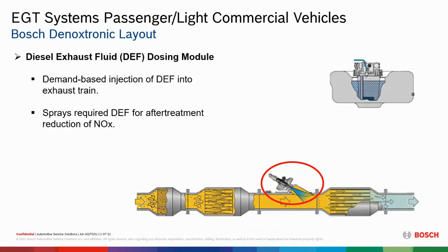And the reason I'm saying that is it's happened. These sensors may fit into another dosing unit if you take it apart. Unfortunately, some of them are very similar. They don't look any different, but the part numbers are different. So it causes performance problems, and it really drives a technician in circles, just trying to figure out what's wrong with it if it's the wrong part number, because you have to disassemble it, match the part numbers up, and so on. It's the last thing you would think of that anybody would do, is put the wrong part number in there, but it happens. So just something to keep in the back of your head when you're working on these.